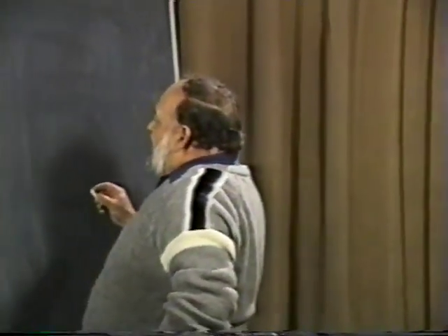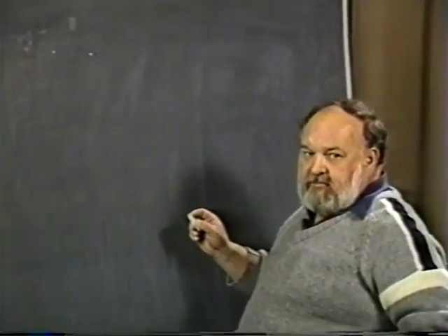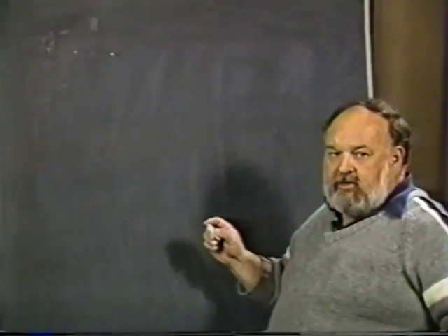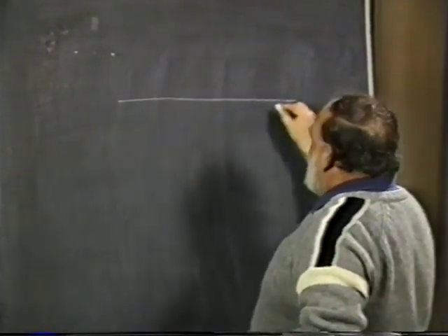There are a couple of key things you ought to be certain you understand when you're dealing with an all-flying tail. Let me go over to the board here and I'll show you just exactly what I'm talking about. It can be done other than using a symmetrical section, but it's strongly recommended that when you go to an all-flying tail, you use a completely symmetrical airfoil section.